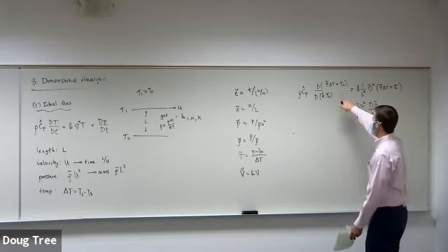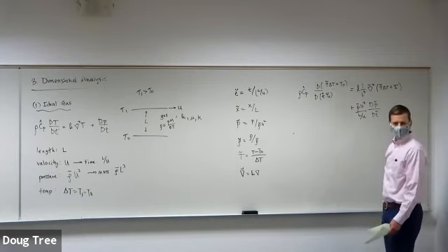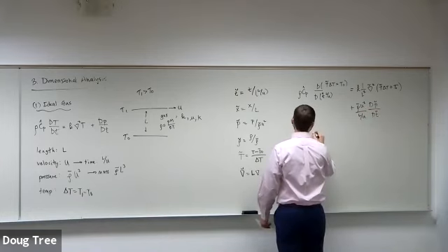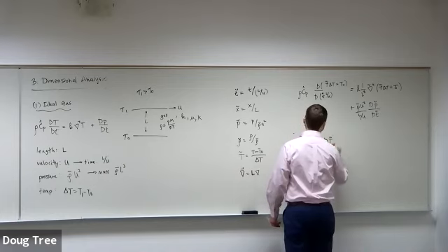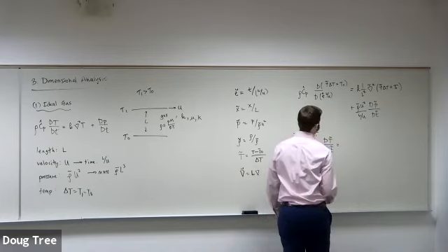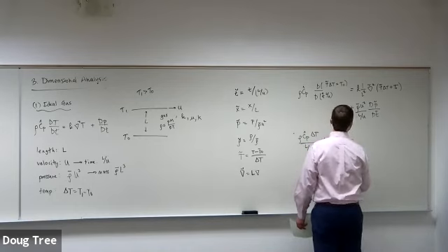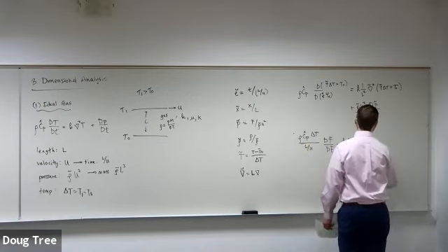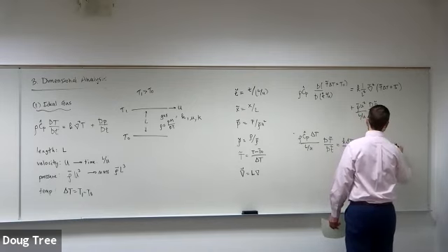So the nice thing about the derivative of the constant T naught is that it goes away. Okay, so I just get out the delta T's. So let me rewrite that. Rho C sub P hat delta T divided by L over U, dT tilde over dt tilde, is equal to K delta T divided by L squared, grad squared T, plus rho hat U squared over L over U. I kind of already did that one.